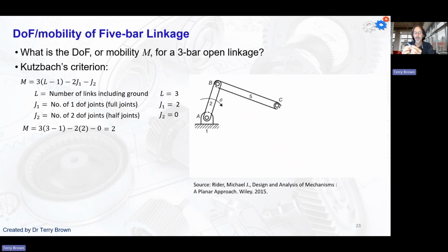So in terms of kinematic control of the motion, if it was something like a robot arm, we need to have a motor at the bottom, a motor here, and a motor here, at all of those hinge points, to control what's happening with that mechanism.